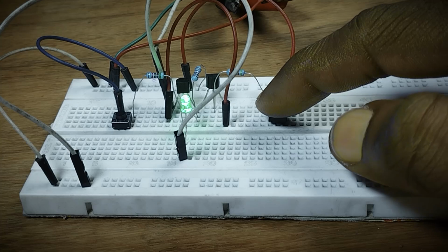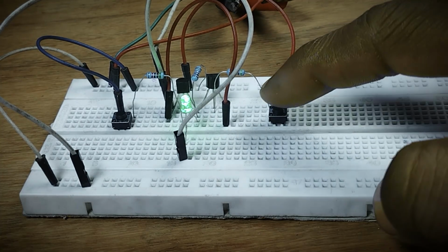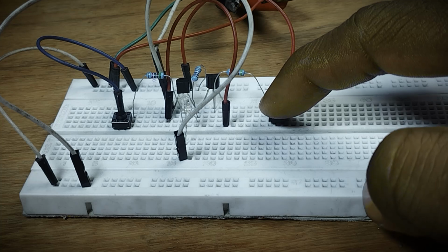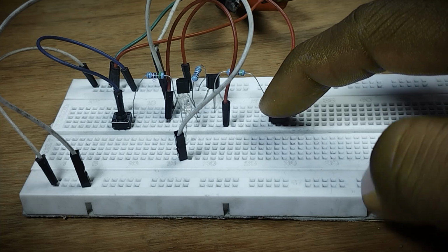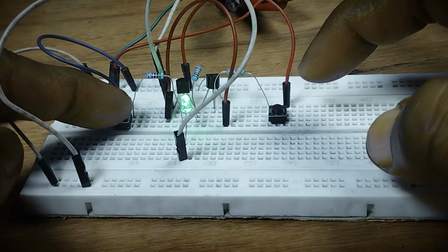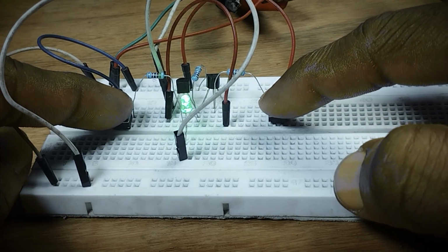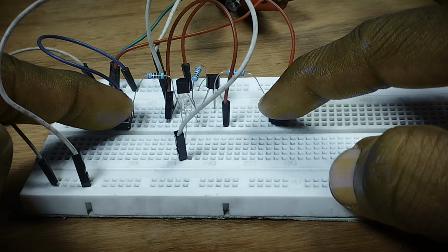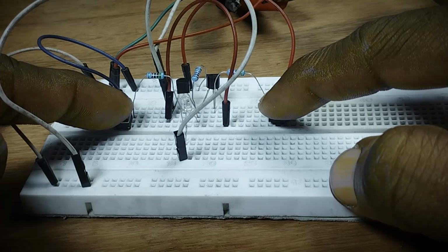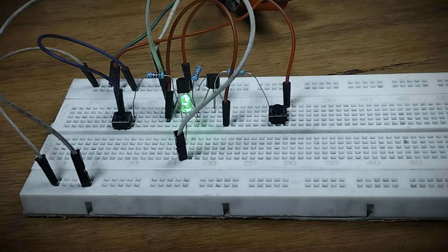Okay, so it's turned on, our output is high. If we send a high signal to the base, we have it turn off. If we send through the other base, we have it also turn off. If we have both of them high, both bases high, we have it turn off. Okay, so this is more like the opposite of the OR gate.